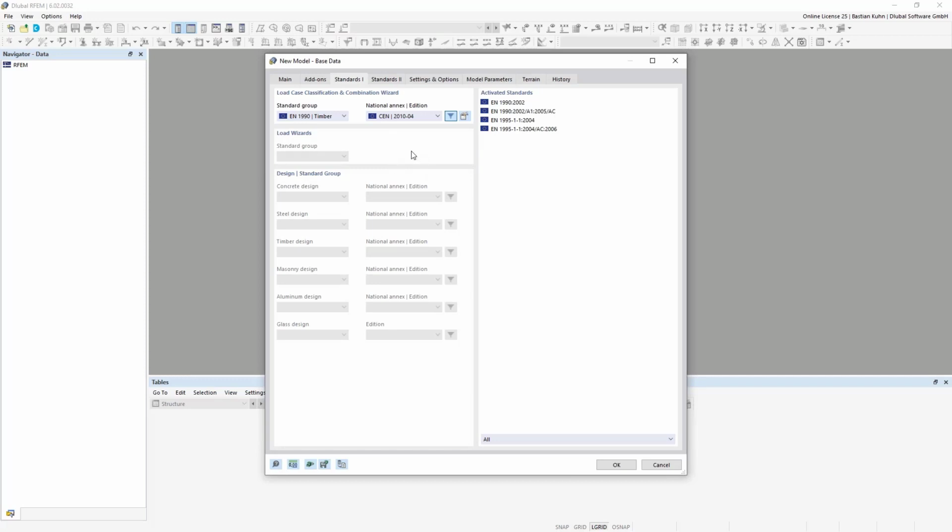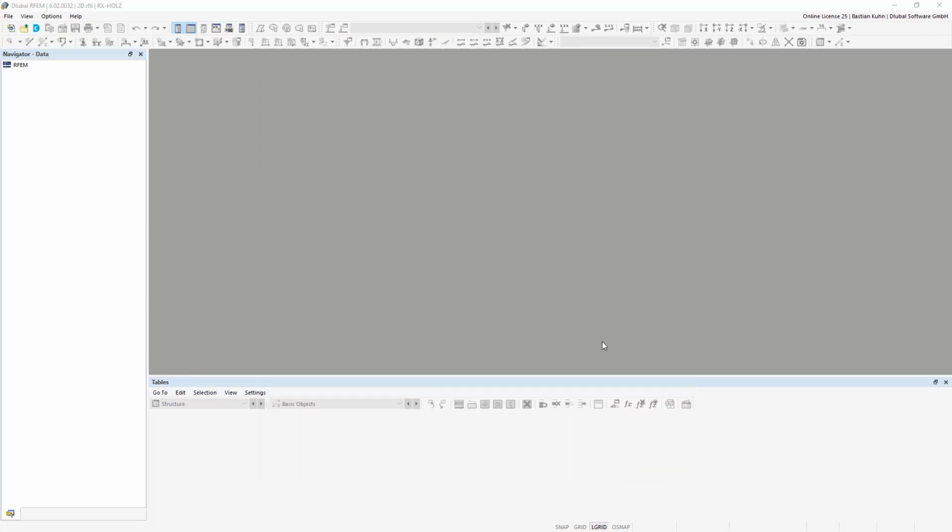It's also possible to do this on the stiffness side, because creeping is actually not an increasing of loading, but an additional deformation that you need to regard. So for a nonlinear system, this approach is not always sufficient, but it's a simpler approach. And for the structure we will build here today, it's good enough. I just want to show you how to regard it. Okay, then we